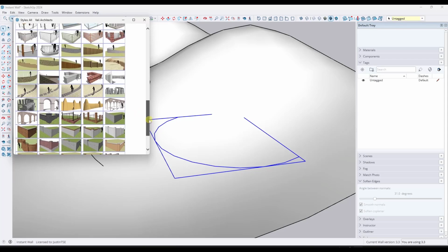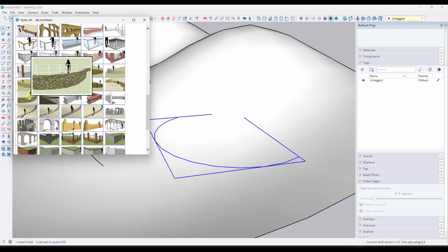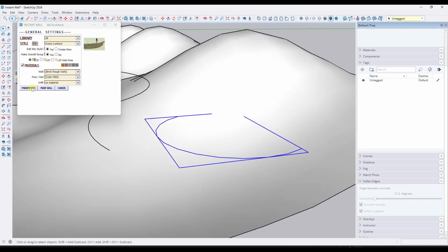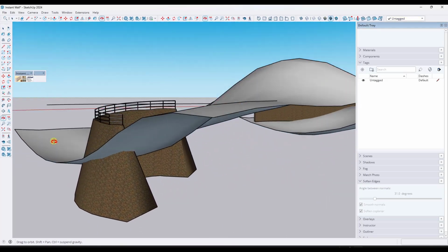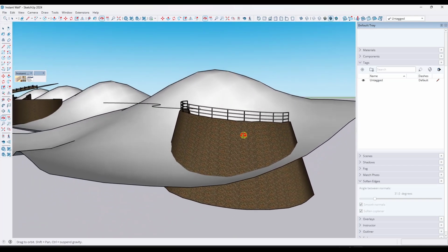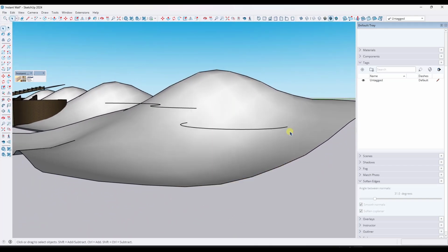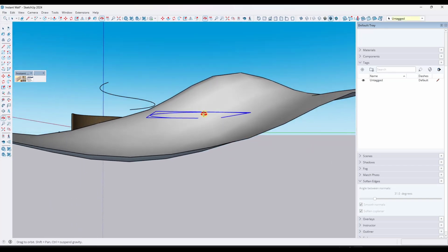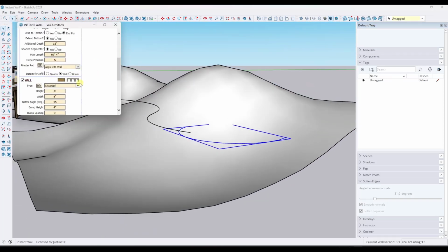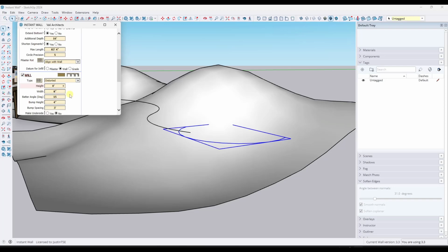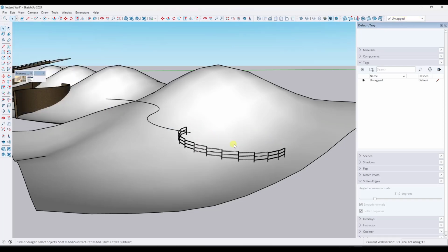I'm looking for it right now, but say this one right here, what this is going to do is create this scenic lookout one. But if I click on make wall right here, that's going to create this retaining wall back in here, and it has that additional height, which we actually didn't really need because this is probably about the proper height in here. So we'll go back to our parameters and reduce this to maybe actually 0 feet. Let's see what that does. I have not done 0 feet.